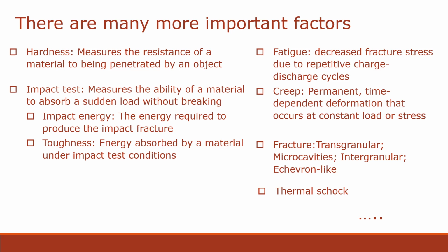The impact test is also very important, it measures the ability of a material to absorb a sudden load without breaking. Then factors which are important in this kind of test are the impact energy, so it's the energy required to produce the impact fracture, and the toughness, which is the energy absorbed by the material under these conditions.